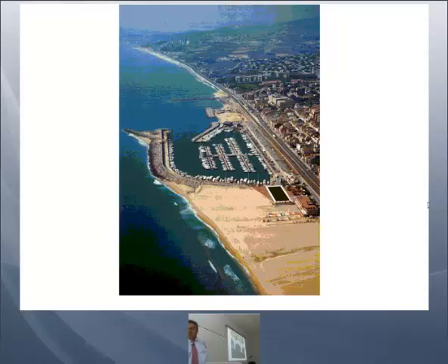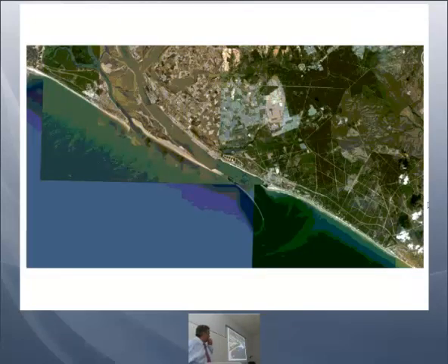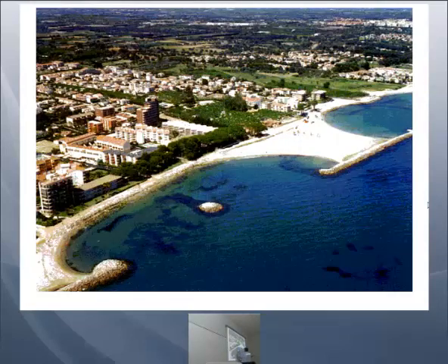If you understand how this thing works, you can modify the coastline in any way you want. Using structures that modify the energy content of the waves, and knowing that the energy is moving the sand, you can make nature put the sand where you want by playing with the energy arriving at the coastline.